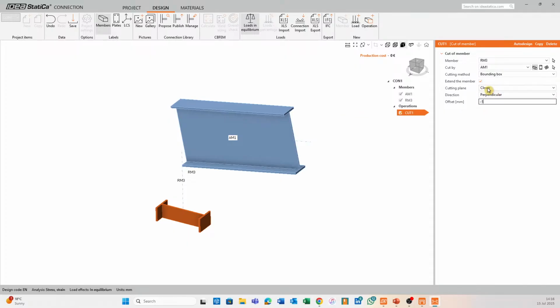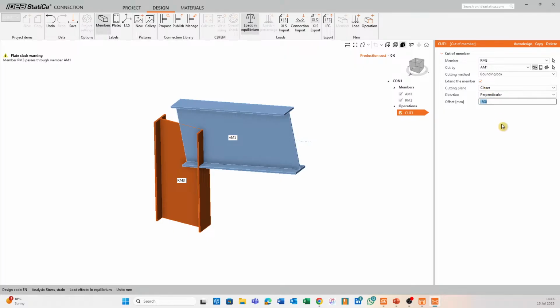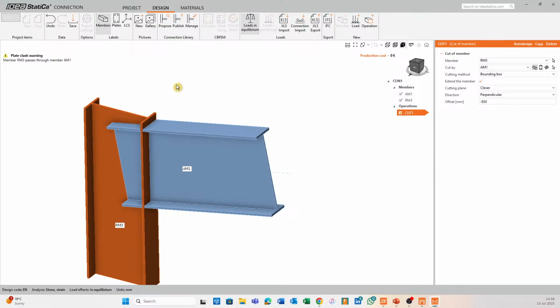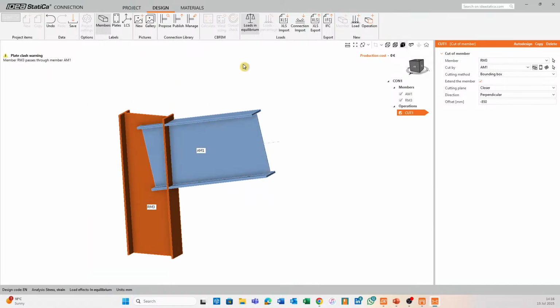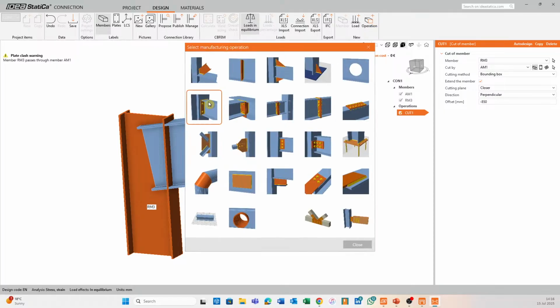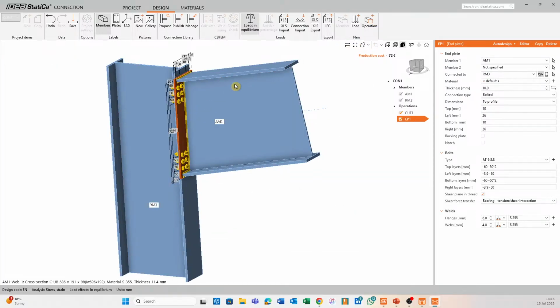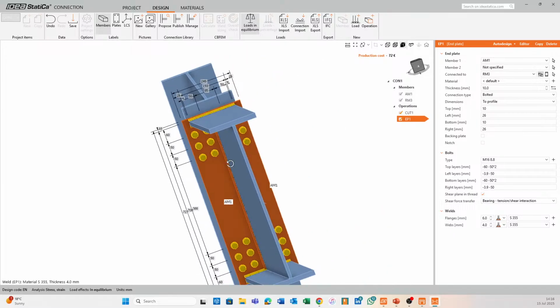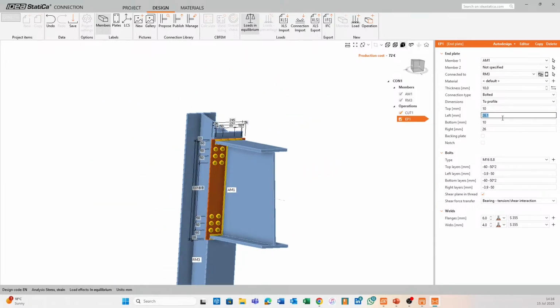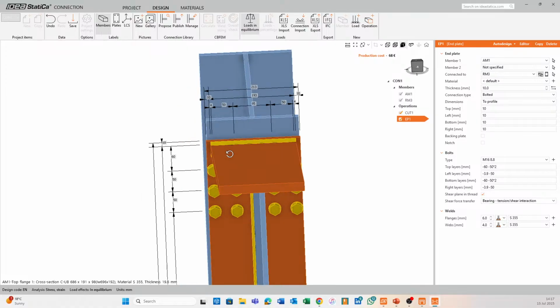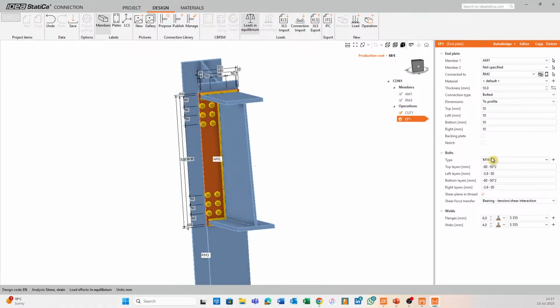Yeah, that's all good. Depending on the option that you choose, your offset direction might be negative or positive. All right, so this is not a problem. Those plates passing through each other is really not an issue. I'm just going to go for an end plate. And there we go. Okay, so there's our end plate. It puts some geometry in automatically. We can modify that quite easily. So I maybe wanted to just extend a little bit. Let's see. Yeah, that's okay.